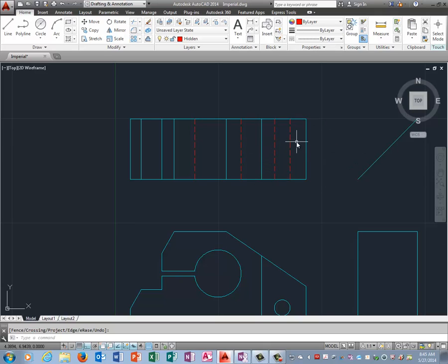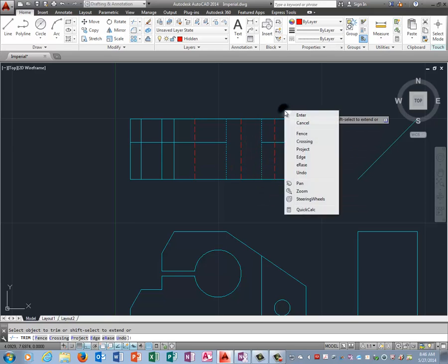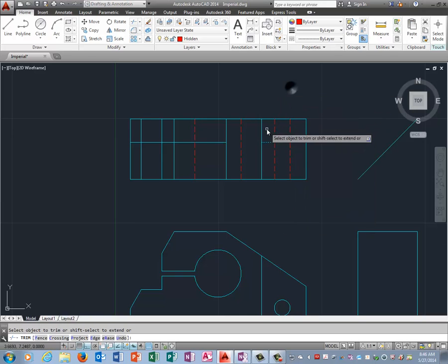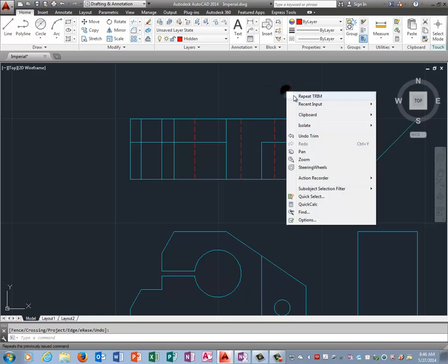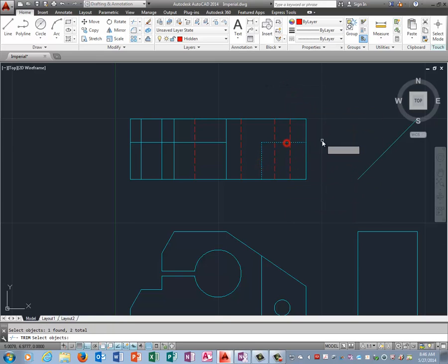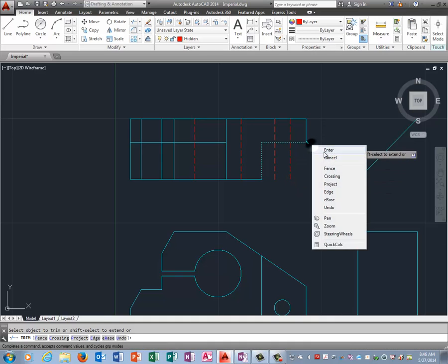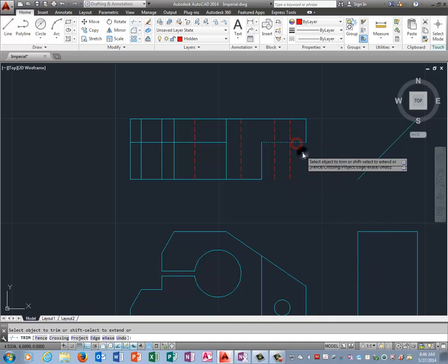And it tells me that from here to here, where that line is created, is 0.56. So I'm going to offset 0.56. Okay, and you can see this L piece here. That's that sloped surface in the top view. Okay, so I'm trimming. Okay, and this whole little piece here is coming out. Okay, and top view. We get rid of that.